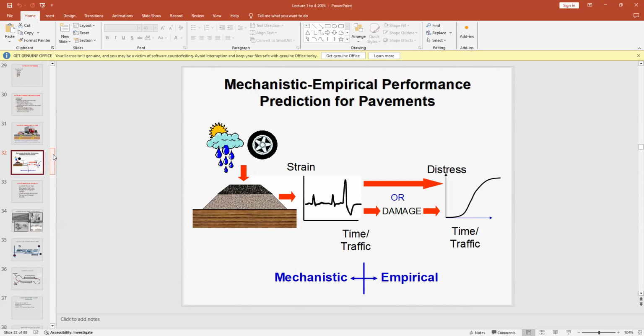When you select a particular grade of an asphalt, it means you are taking care of its potential in the different hot temperatures. For example, we use 60/70. The people who have a colder climate may use 85/100 as well. But if the countries have a hotter climate, on average hotter, then they may use 40/50.